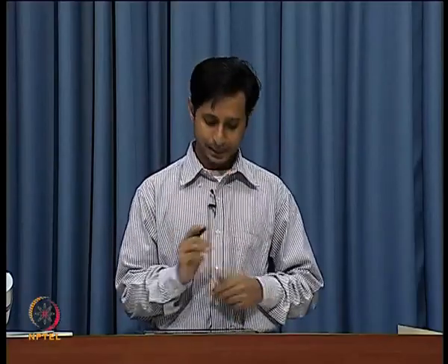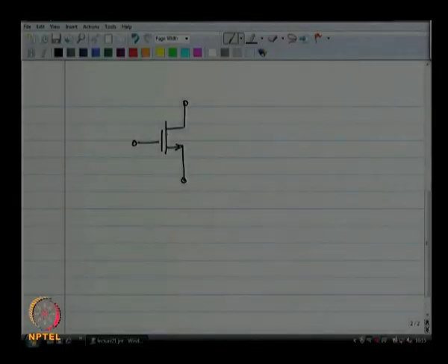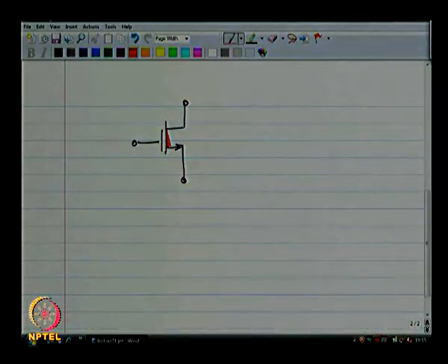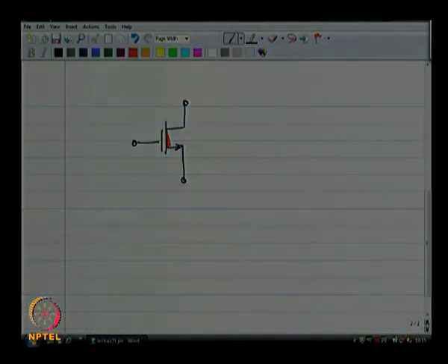All of these electrons are bouncing against each other, jostling, fighting for space. I have tilted the channel in favor of the source against the drain, because typically the drain voltage is going to be larger than the source unless you are using the MOSFET as a switch or in its linear region. We are not going to use the MOSFET as a switch, that is why I have tilted the channel in favor of the source, it does not really matter.